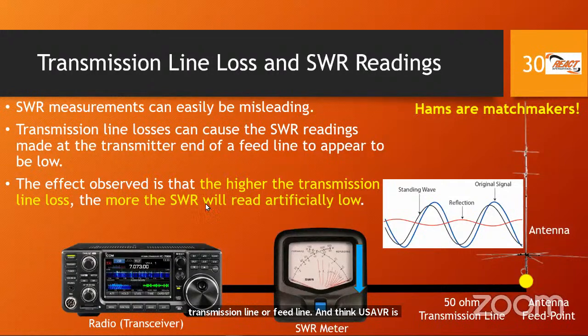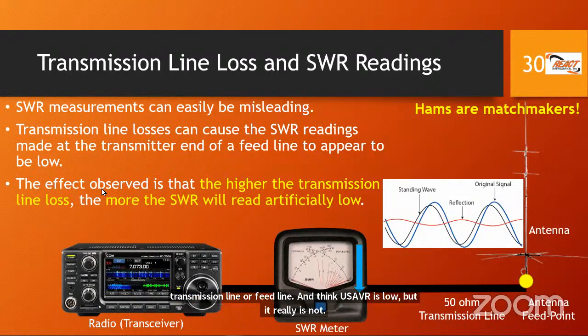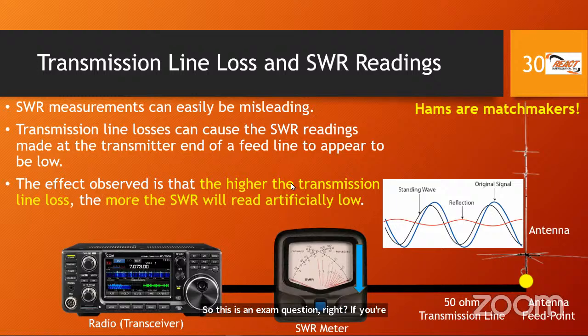So this is an exam question, right? If you're using poor quality transmission cable with the higher transmission line loss, the more your SWR will be reading artificially low, and that's an exam question. So bear that in mind.